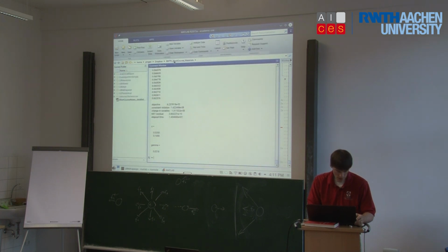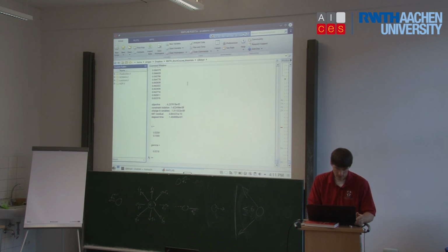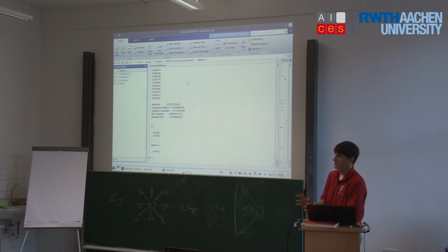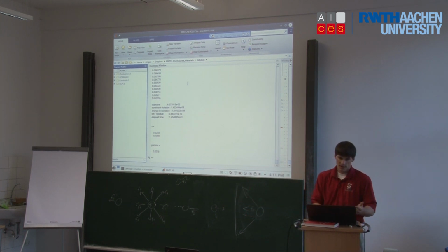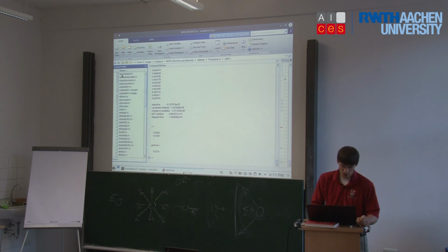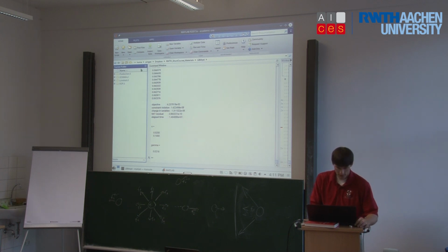So the optimization code is in LBM opt. Okay. And when you run this, it's important that you set the whole directory into your path. Okay. So in Matlab, everything we've had so far, all functions that we used were in the same directory as the function that we executed. Okay. In this case, there's subdirectories, and there's an SCP algorithm. There's a GCMMA as an alternative. We'll look at an example in a second. And then there's a fluid solver, which has the Lattice-Boltzmann code underneath it. And then there's some utilities, kind of the input file, the driver file. And then there's some level set stuff, which I have disabled at this point. But it's still kind of in the code, but there is a level set function, but I didn't want to deal with it for the purpose of this talk.